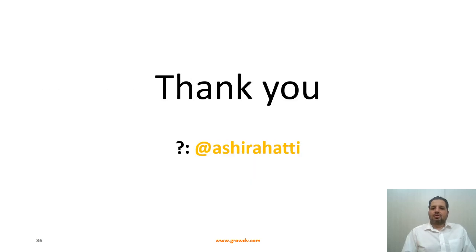Okay, so this concludes the section on SystemVerilog based randomization. We saw three different categories of items in the context of SystemVerilog randomization. The first category, wherein we defined a class containing the random variables and a set of constraints, and called a randomize function.